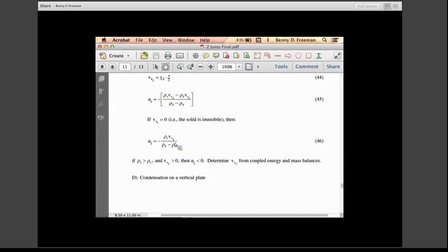And so essentially, as the CO2 vaporizes and leaves that interface, the height of the solid decreases a little bit, right? And that interface velocity u_c is the velocity of that solid-vapor interface. So as the CO2 evaporates and goes up, the interface must go down a little bit. The interface moves in the opposite direction to the gas phase. And what is the coefficient of proportionality between them?